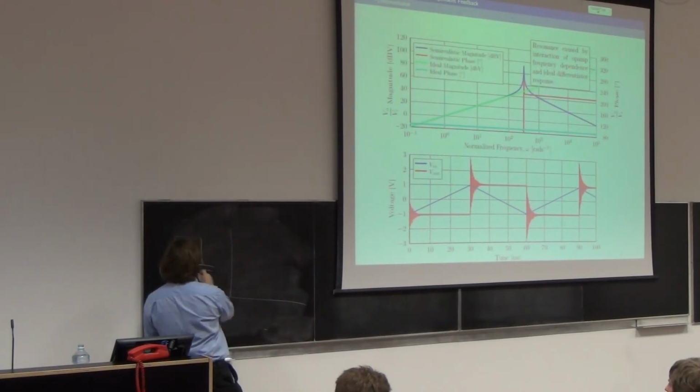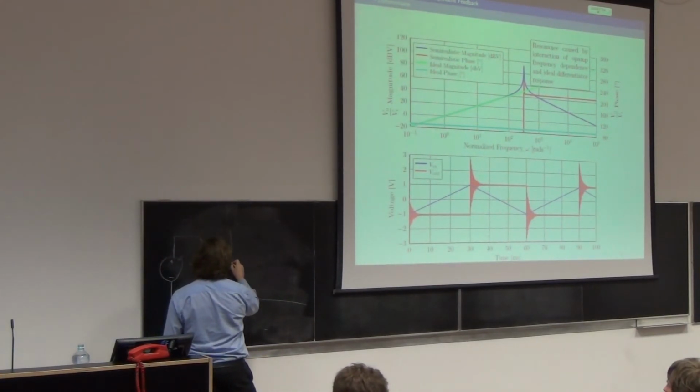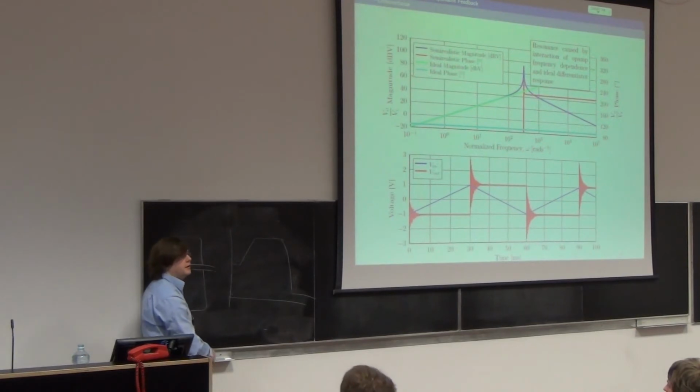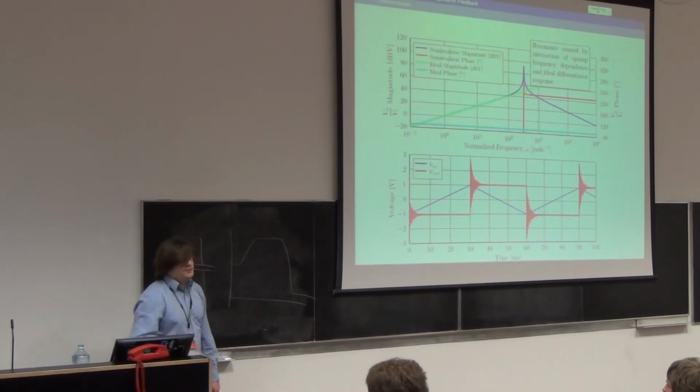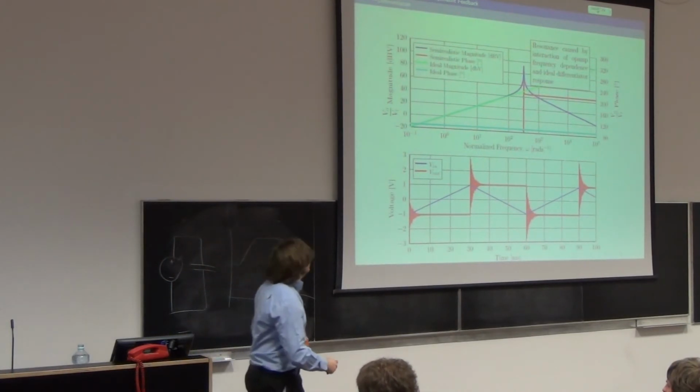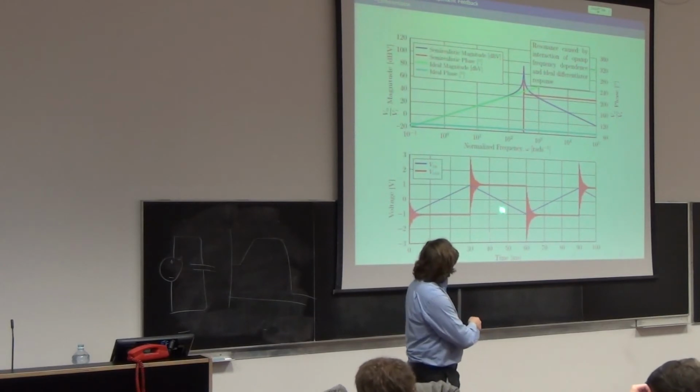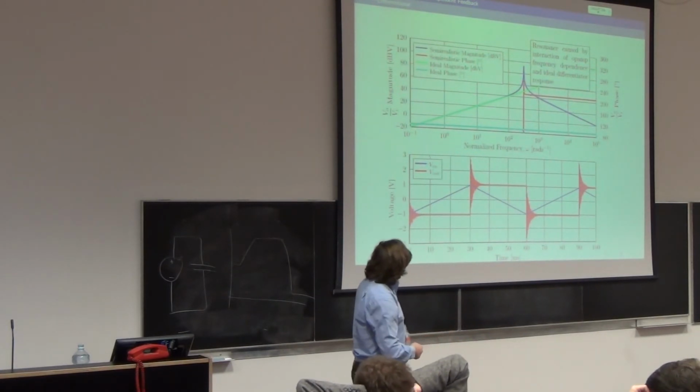I said the voltage on the capacitance is going to do something like this. What will the current look like? It's just a differentiation thing. They all screwed it up, I don't know how. Anyway, never mind. So if I was to differentiate the triangle, I'd get the square.